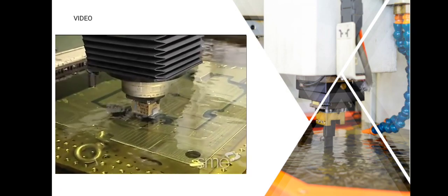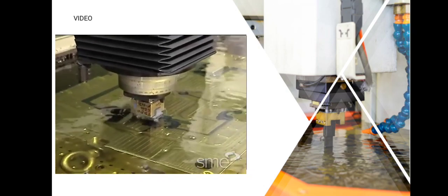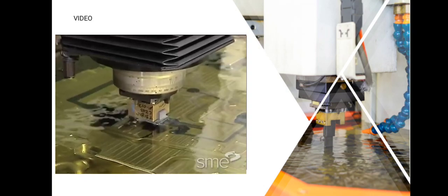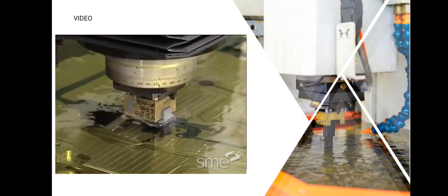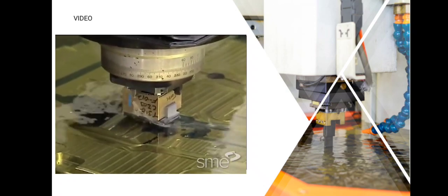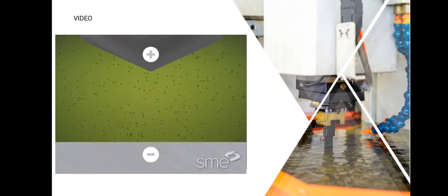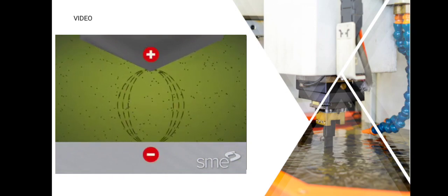As erosion continues, the machine controls advance the electrode through the work, always maintaining a constant gap distance between it and the workpiece. To understand how EDM removes metal, let's examine a single spark in the erosion process. As a pulse of DC electricity reaches the electrode and part, an intense electrical field develops in the gap.